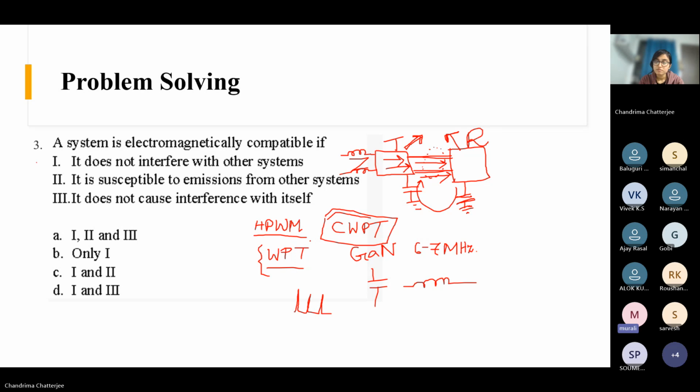For example, one scenario I can tell you: we should not take any mobile phones inside, but once by mistake we did. With that setup and the spectrum analyzer, we identified that there was some Vodafone mobile nearby. Then we confirmed, yes, there was a mobile like that. So for non-intentional emissions, we have to create multiple sniffing setups to identify them, because wireless is not visible and so it is very difficult to identify.